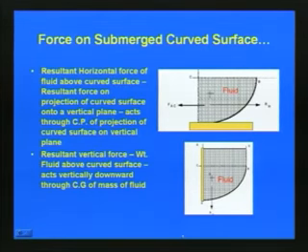Similarly, in the case of the vertical component, as far as this gate is concerned, the resultant vertical force will be the weight of fluid above the curved surface. So, here we have the curved surface. What will be the weight of fluid above this curved surface, that we can determine, and then that acts through the center of gravity of the mass of fluid. So, here the mass of fluid is just above the curved surface.